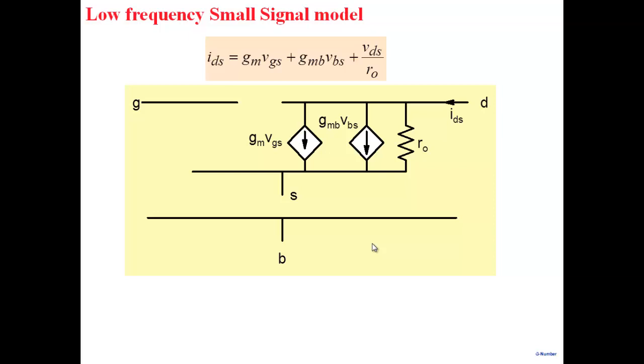Okay, the diodes are reverse biased, and the small signal model of a reverse biased diode at low frequency is just an open circuit. Reverse bias current, to first order, does not vary much with the voltage, and therefore the reverse bias diode becomes an open circuit here. The reverse bias diode which was there also becomes an open circuit. So that's how your MOSFET looks under small signal.